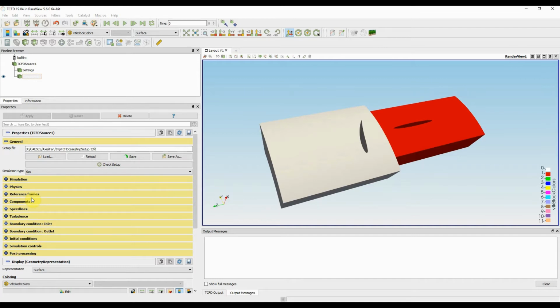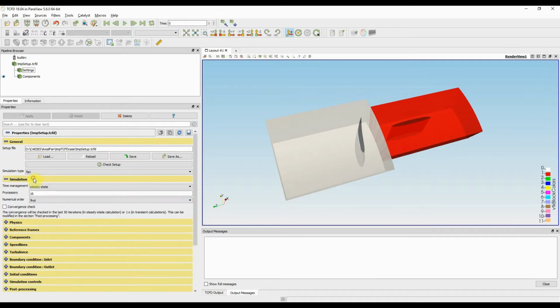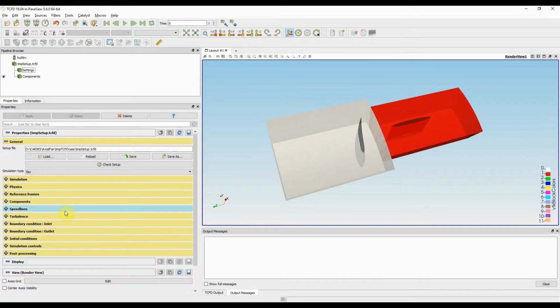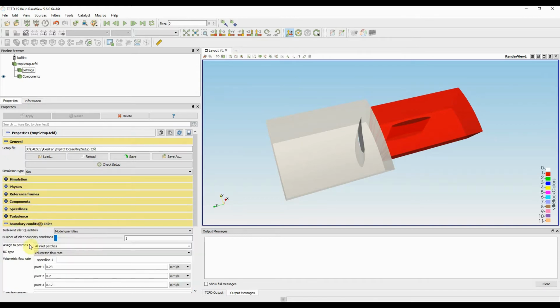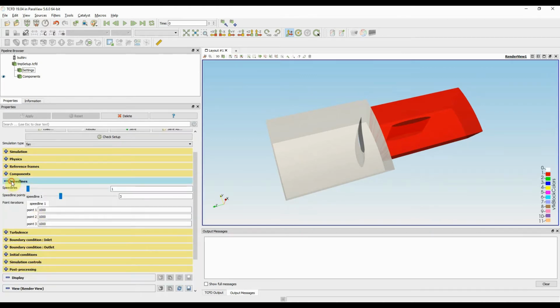Let me now jump in time a bit. I have tested my setup, run the simulation, and redefined the mesh to follow all the aspects of CFD, and now I am ready to run the final simulation. Everything is preset. I will be using 16 processors because my computer has 16 physical cores. I set 3 points to be simulated with different volumetric flow rates to see a short performance map for my Excel file as an example, and the revolution speed